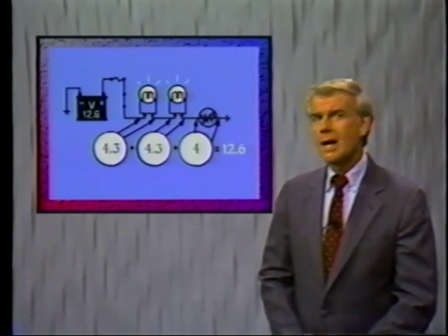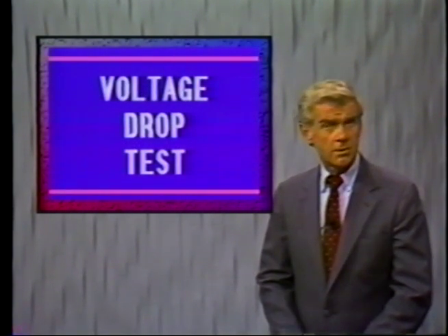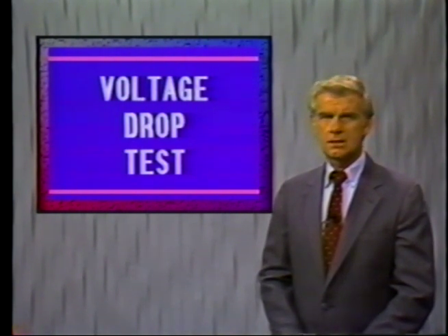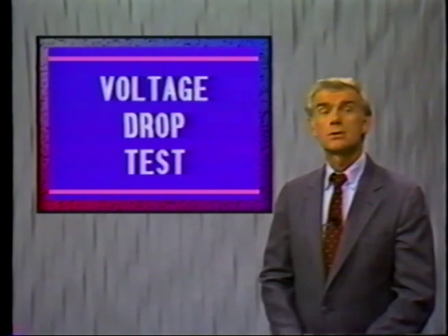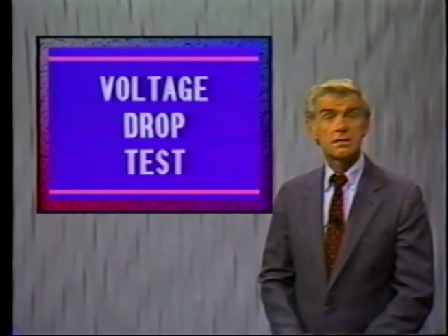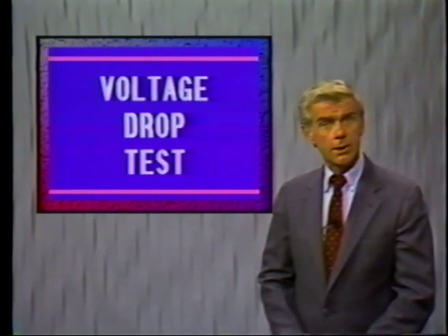The key to locating high resistance is the voltage drop test. Performed with a voltmeter while the problem circuit is operational, this test quickly isolates faulty connections, high resistance switches, and ground circuit resistance. Under ideal conditions, at the load device in the circuit, we want all the current and voltage that's available at the battery.